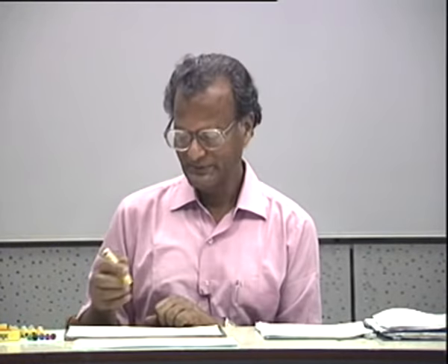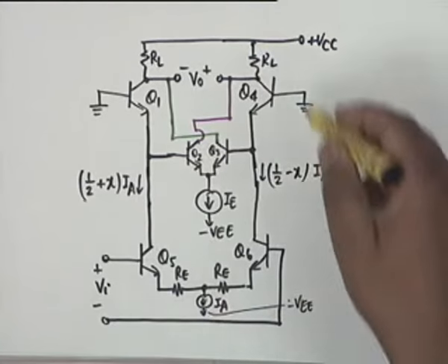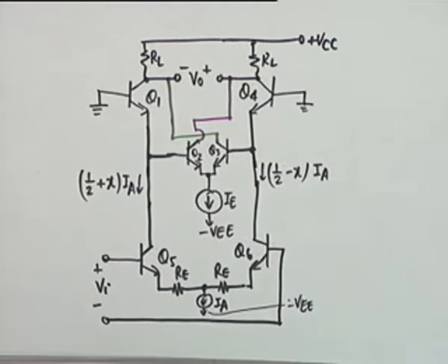In an op-amp, in an IC chip, there is no ground terminal, there is no reference. An op-amp does not provide a reference. It provides several terminals: 2 input terminals, 1 output terminal, 1 for positive supply, 1 for negative supply. Where is the ground then? The reference is between the common point of the two supplies, plus VCC and minus VCC. Usually they are equal. Okay, and therefore since two supplies are available, the differential amplifier is based on that.